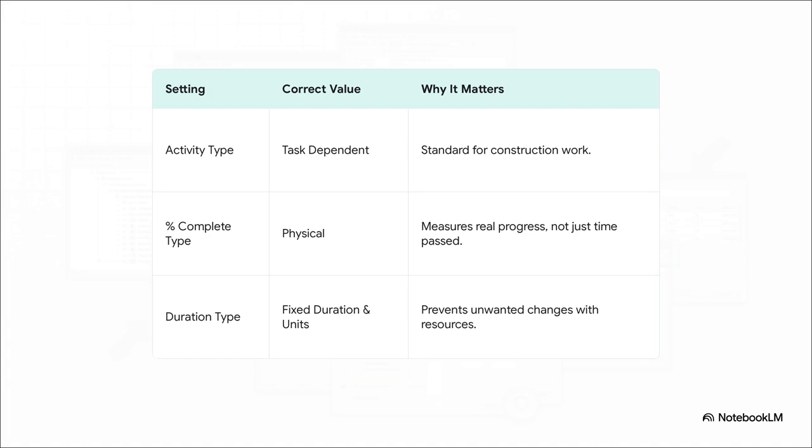Think about it. For MEP work, we measure progress by installed quantities: meters of cable, lengths of duct, number of fixtures. We don't care how many days have passed. Using duration %complete will just hide the truth about where your project really stands.